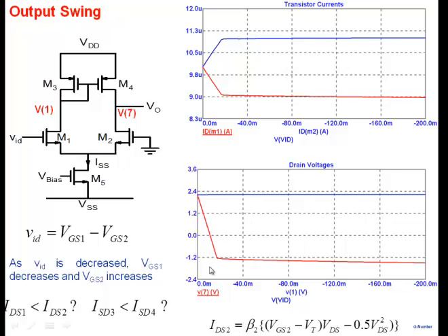So this is what is happening. You can see here V7 starts to change. The moment it goes here rapidly, after that V7 is not changing with input voltage here. This is the output, which means there's no gain. So there's a gain till this point here. V7 is changing here. So there's a gain in this particular part, but once it saturates, then there's no gain.